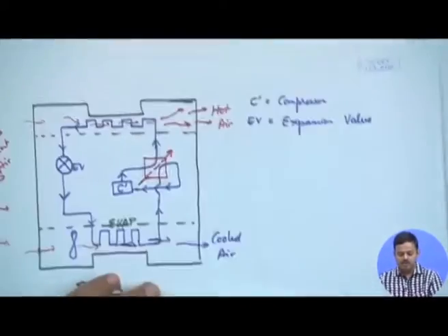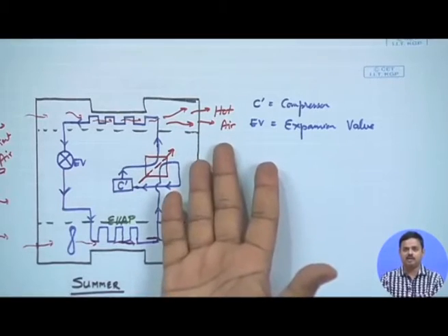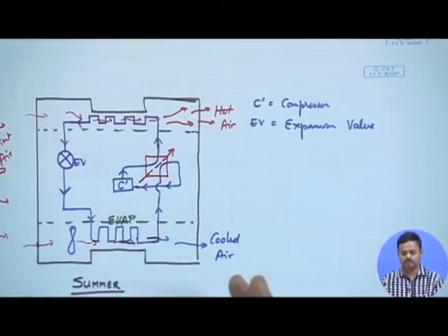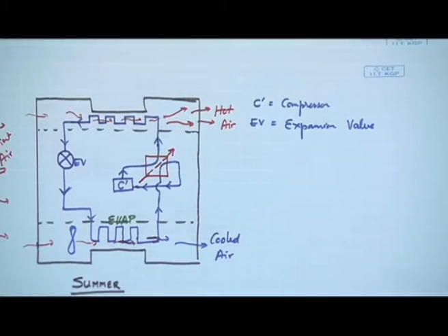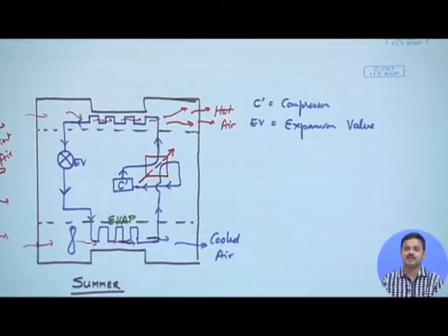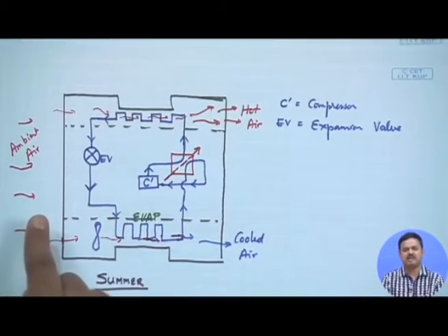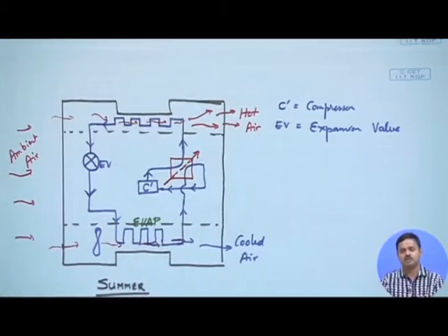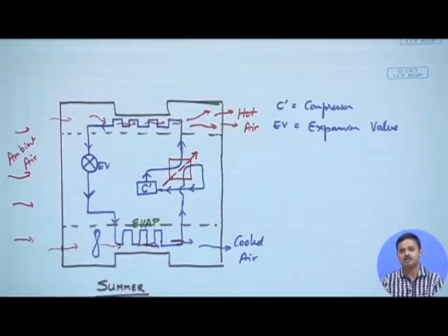And similarly, over here when you get hot air in summer months, if you are again talking about a small industrial enterprise, hot air has lots of applications. If nothing else, this hot air can be used for a vapor absorption refrigeration cycle, which you have studied. I have upgraded the heat energy from ambient, which was probably at around, let us say, Delhi summer will be 40-45 degrees centigrade. I can upgrade it to almost 70-80 degrees centigrade. Use this for something useful, for waste heat recovery.